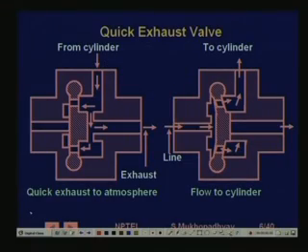So, these valves are sometimes used when you do not release the air at the direction control valve. The air is driven by the direction control valve, but is released right at the actuator using a quick exhaust valve. You can see a construction here where, when you are driving pressure into the cylinder, these are typically connected with cylinders, this is the basic mechanism.